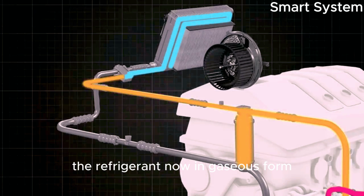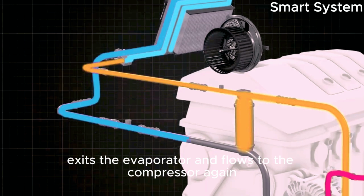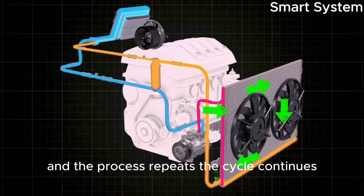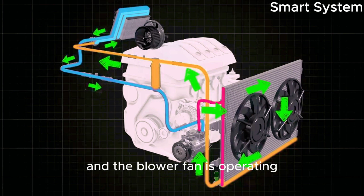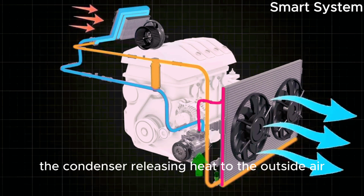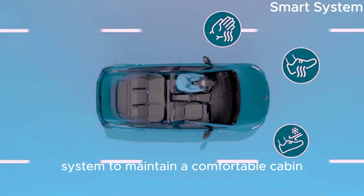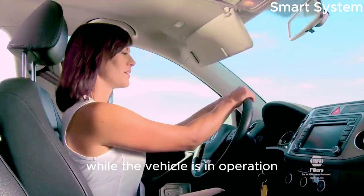The refrigerant, now in gaseous form, exits the evaporator and flows to the compressor again. The compressor receives the low-pressure gas, compresses it, and again sends it to the condenser, and the process repeats. The cycle continues as long as the AC system is turned on and the blower fan is operating, with the evaporator absorbing heat from the cabin air, the condenser releasing heat to the outside air, and the expansion valve controlling the refrigerant flow between the two. This continuous cycle allows the AC system to maintain a comfortable cabin temperature and humidity level while the vehicle is in operation.